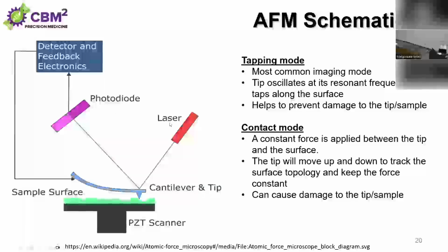You can see what happens. The measurement process is actually quite simple. You're looking at the deflection of this tip as it's going over this rough surface. If I shine a laser on that, it generates a pattern on the photodiode that's indicative of how much that tip is bending. That'll give you an indication of the topographical features of this surface. And the sample is put on a piezoelectric scanner. It gives you very good XY resolution.